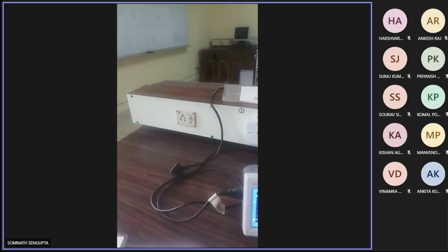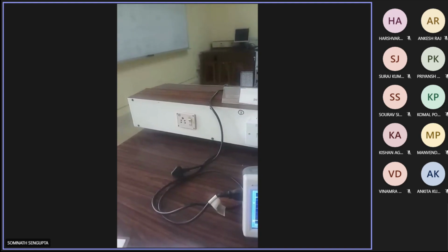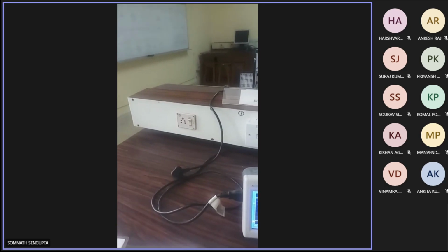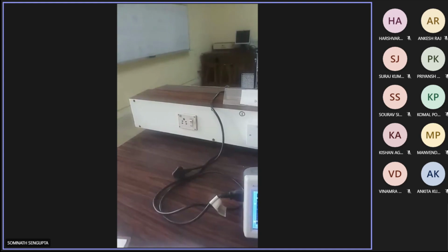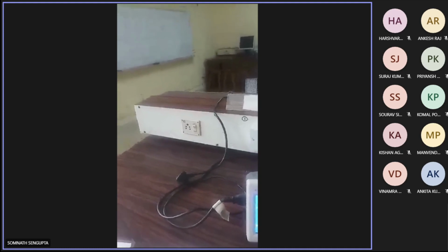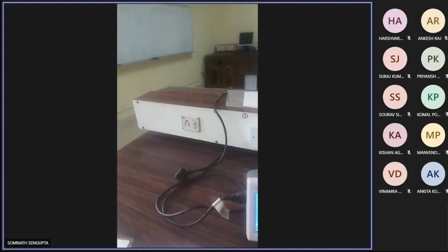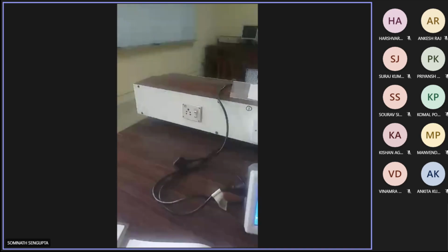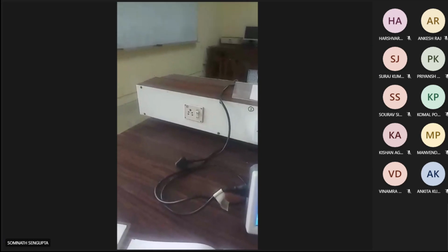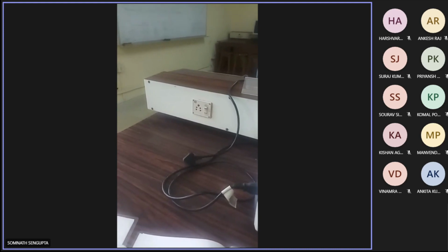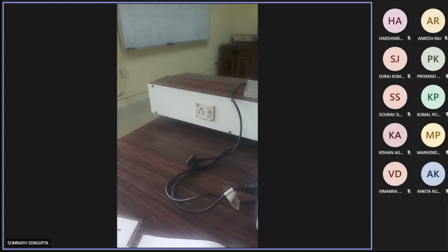Then the triangular wave and the received data itself are XORed. The XOR gate will produce a low going narrow pulse at the edge of each transition, and the edge of each transition actually tells about the clock pulse. So that means a clock pulse is present at those locations.